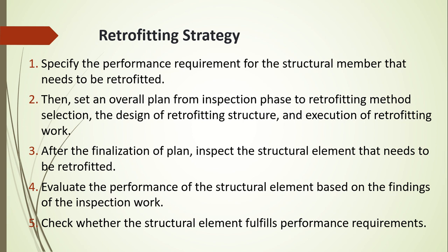Then this retrofitting strategy. This strategy is to be followed in any type of retrofitting work which has been carried out in a beam or a column or a joint, etc. First, specify the performance requirement for the structural member that needs to be retrofitted. So what is the performance you are expecting from the structural member that is going to be retrofitted? How long you want this column to exist, or how much load capacity this column should withstand? All these factors should be specified.